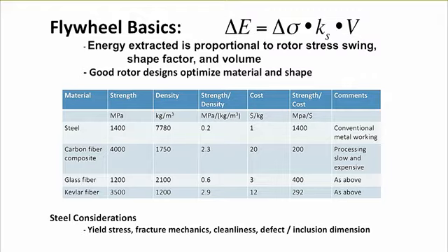And there's a little bit more in there in that the change in stress state is actually, for the detailed people, the sum of the principal stresses integrated over the volume. So there are details with respect to whether we're talking about uniaxial stress, as in a fiber type hoop, or biaxial stress, as in a solid type device. But that's very detailed stuff.